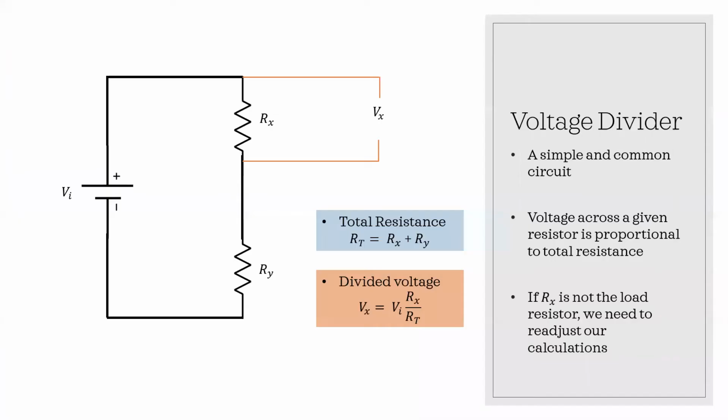So what is a voltage divider? A voltage divider is two or more resistive components in series with a voltage source. We know that voltage supplied to a circuit is split up proportionally between the components that are in series with each other and the source.